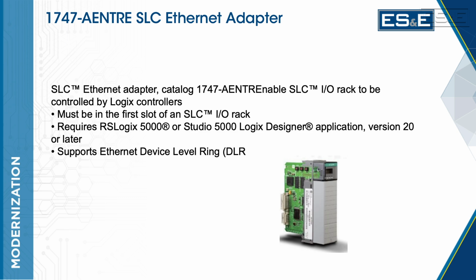The only disadvantage I see is you need to make sure that the cards that you select, see those IB16s right there, some of those? They're grayed out. They're discontinued. So we need to make sure the cards that are in there are not on the discontinued list, right?